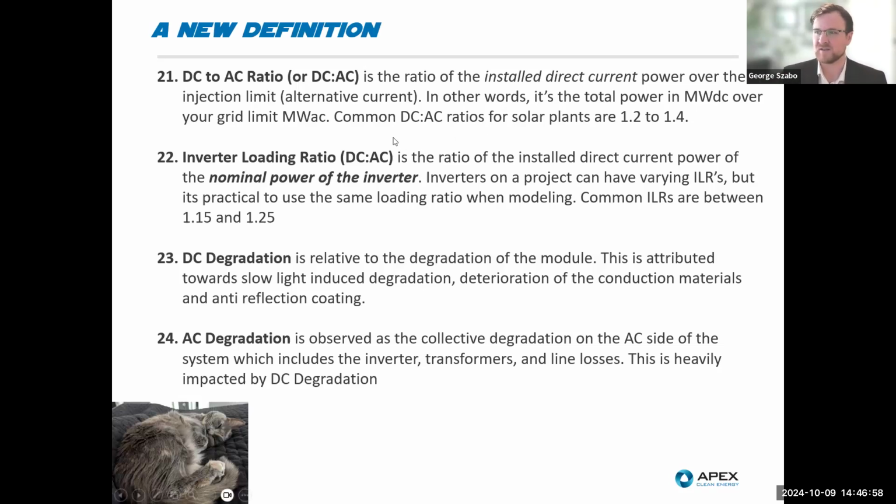That's an example of light-induced degradation. Modules don't get yellow because the glass that they use on the front side is very, very pure. It has a super low iron content, because all of that iron within the glass adds a little bit of reflectivity to it, which we don't like. But it also leads to really low degradation over the course of the module's lifetime.